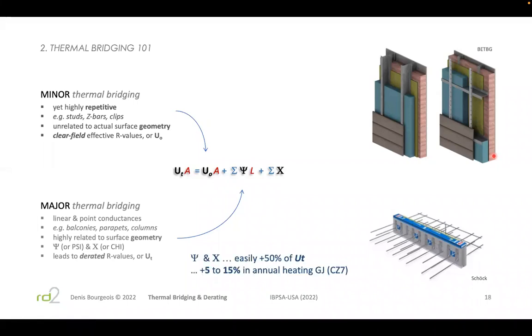How significant is this? Well, it depends where you are in the world and the nature of the building. I'm in climate zone 7 towards the lower limits. So that's ASHRAE climate zones. So that's about 5,000 heating degree days. This would be the same for any location that's in climate zone 6 towards maybe 4,500. So those would be in SI units. So anyone having 4,000, 4,500 heating degree days, minus 20 C or minus 25 in terms of heating design temperatures, that would be like minus 13 Fahrenheit.